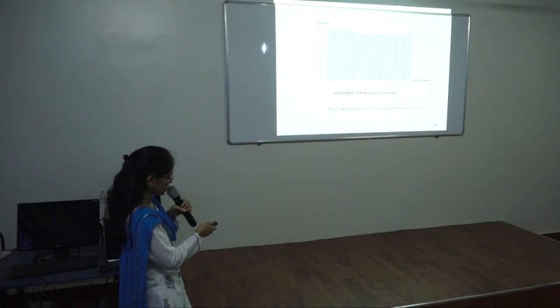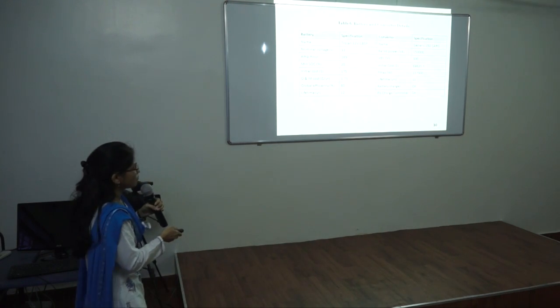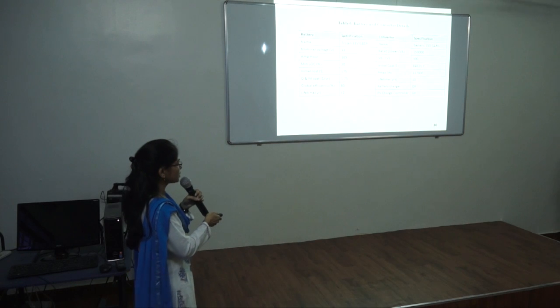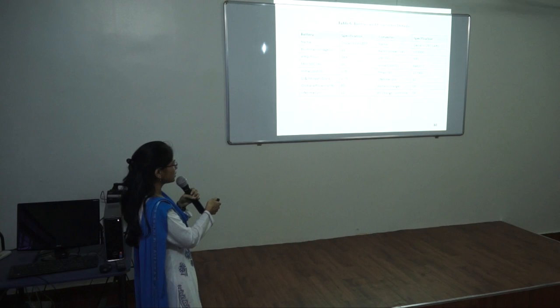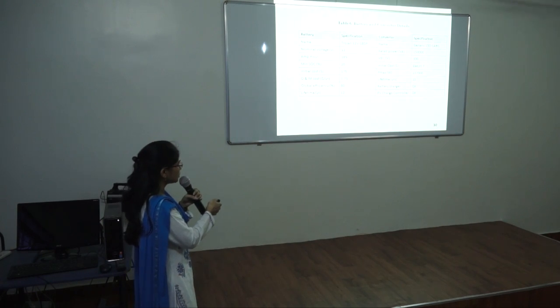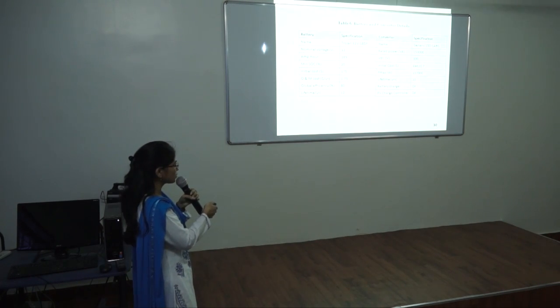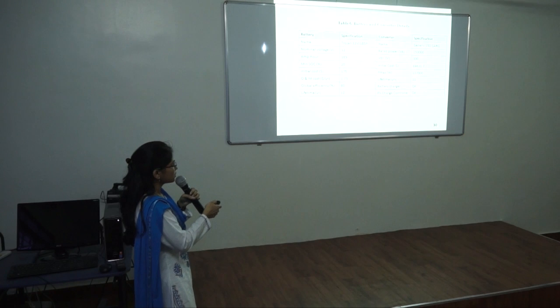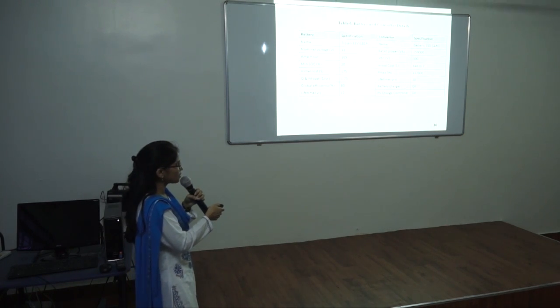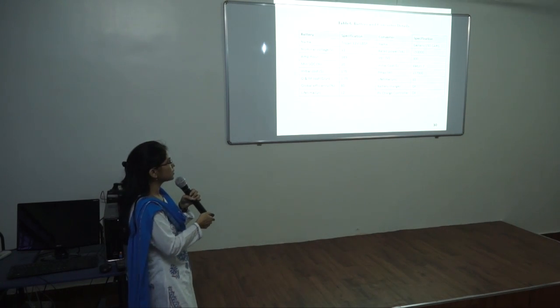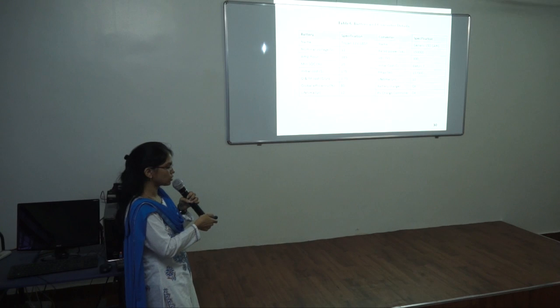50 kilowatt wind generator. For storage purposes, the battery is selected with a nominal voltage of 12 volts, 189 ampere-hours, with a minimum state of charge of 20% and a global efficiency of 80%. The converter is selected with 150 kVA and a DC voltage of 300. This converter contains the battery charger as well as the PV charge controller.